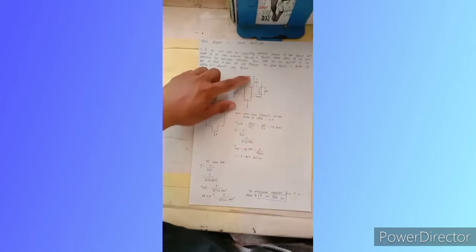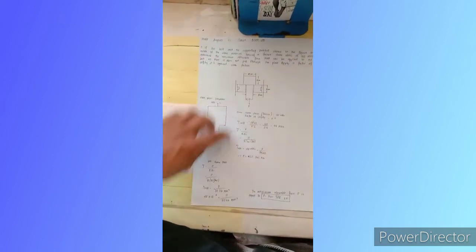So, P is equals to P. Apply ulit natin yung 80 mm times 30 mm sa ating formula. So, our shear stress is equals to P all over pi times 80 times 30. Our shear stress safe is equals to P all over 7,536 millimeters squared.